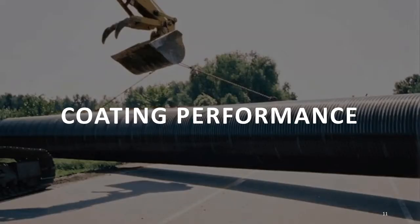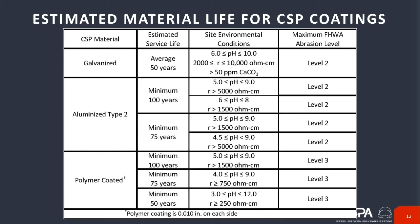Of course, inherent within each of these coatings is its ability to perform in specific environments. Not all coatings are created equal. This table presents the expected service life for each of these coatings based upon the environments in which the products are installed, including pH, resistivity ranges, and the maximum allowable FHWA abrasion level.